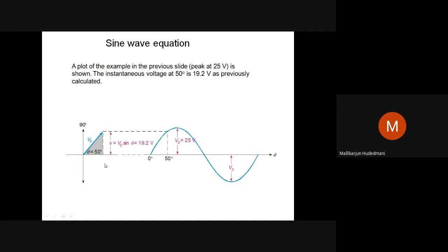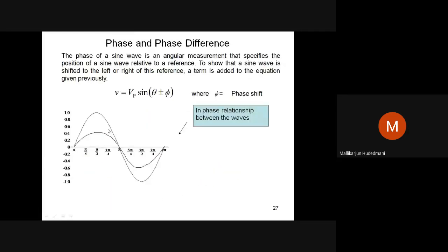Just imagine a circle here. This is rotating. Just remember, I'll speak about that later. This is revolving here, so an imaginary circle is formed. Imagine a circle, and to its circumference this line is touching. Then join that. That is called an angle of 50 degrees. Or this vector stood 50 degrees away from the reference point. This angle we call the phase. Phase of an alternating quantity is the angular displacement that the quantity has shifted.